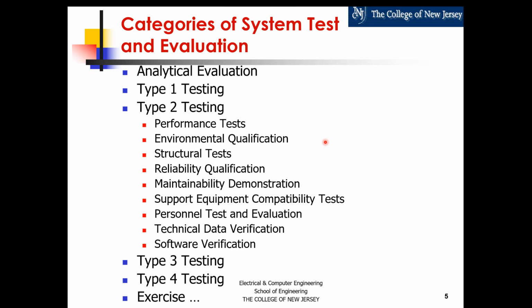Drop tests. Remember, you have a product that's going to be shipped and staged. So what is the resilience of the product to being dropped? Those are important concerns. Temperature variation: there are tests such as temperature shock, where you change the temperature very quickly and see the reaction of the product. You can do shake tests, where you subject the product to sudden accelerations, to vibration. You can subject the product to intense humidity and pressure conditions.